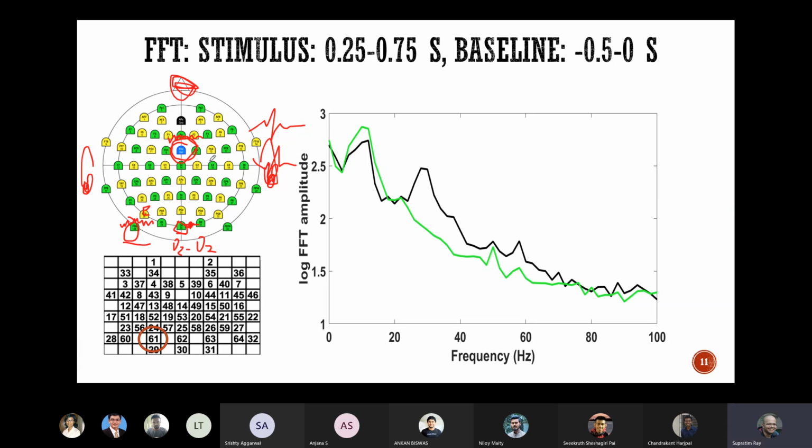Okay, so from these set of electrodes, you can actually think of a virtual array of bipolar electrodes that correspond to, this minus this would be a virtual electrode here, this minus that would be a virtual electrode here, this minus this would be something like that. So you can have a lot of virtual electrodes sitting between the actual electrodes, and the value here is just this minus that, that minus that, and so on, and actually have a bipolar distribution computed this way.